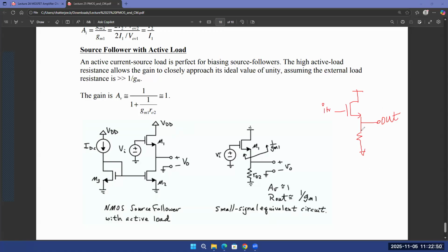Now, in homework problem 6, we saw that we can replace this resistance with a current source because the current source has infinite resistance. The gain in this case is going to be gmRS divided by 1 plus gmRS. Again, something that we had proved earlier, so I'll not go through the proof once again, where RS is the value of this source resistance and gm is the gm of the transistor. The voltage gain Av for this particular source follower configuration is gmRS divided by 1 plus gmRS.